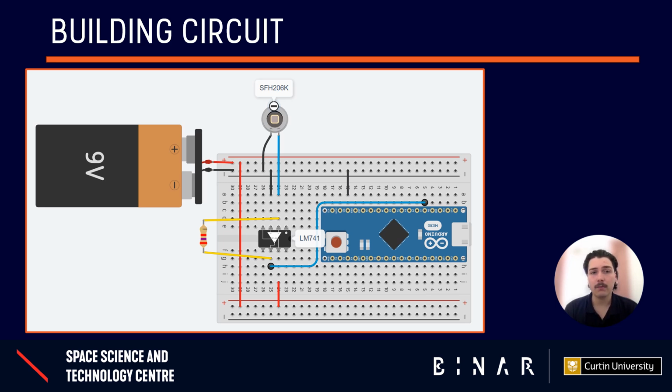Before powering up, double check with your teacher to ensure that all components are correctly placed. Once confirmed, you can move on to writing and uploading the Arduino code. A helpful tip is to color code all these jumper wires. This is to keep your breadboard organized and much easier to troubleshoot if things don't work as expected.